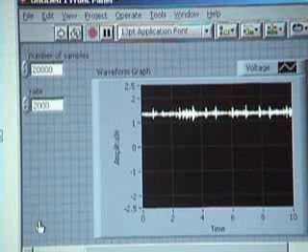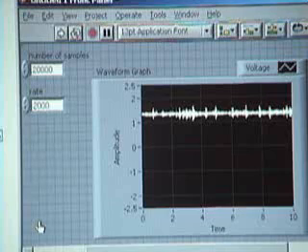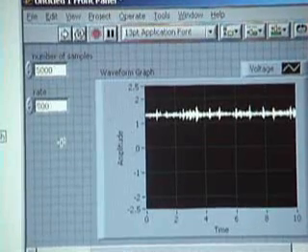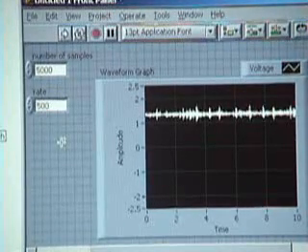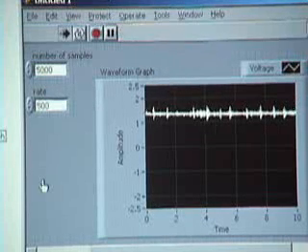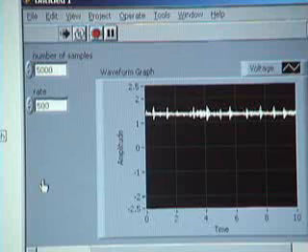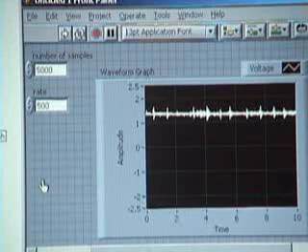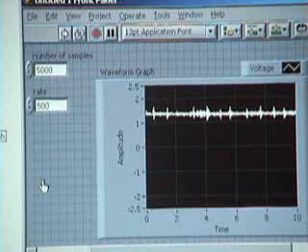Sampling at 2,000 hertz, the music becomes noticeably bad and the high frequency signals get distorted, similar to what you might hear in a very cheap audio device or a video game. So now we're going to sample at 500 hertz, which would capture only the very low frequencies. Sampling at 500 hertz, all you can really hear is the very low bass rhythm of the music.